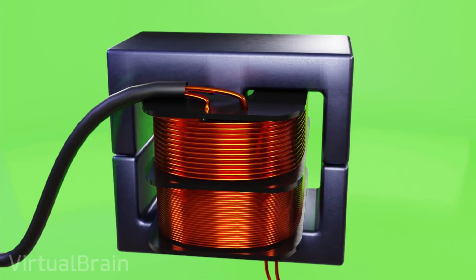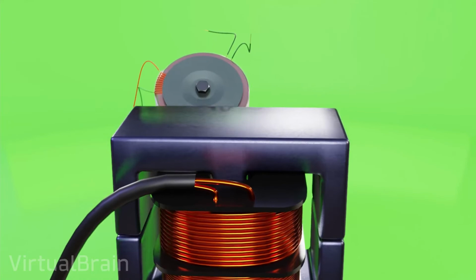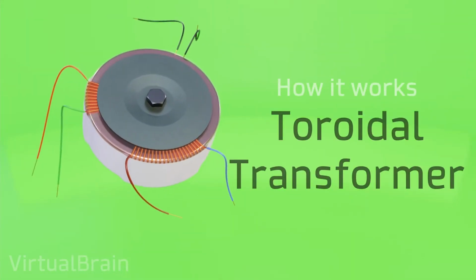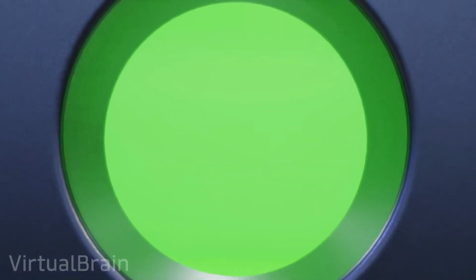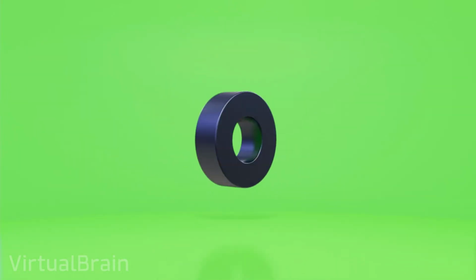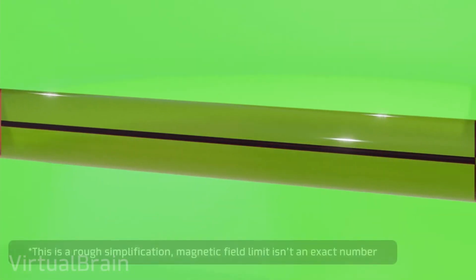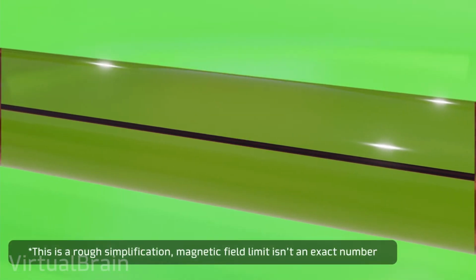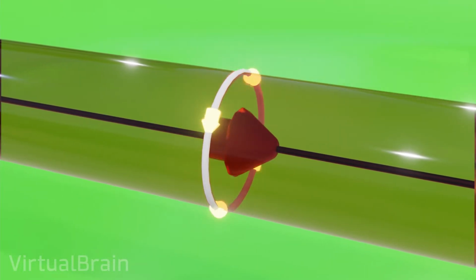But transformers like the ones I showed you in the previous chapter still have certain limitations. And that is why in this chapter we will see how a toroidal transformer works. We will start by analyzing the obvious: why use a toroidal shape? This has to do with the shape of the magnetic field and flux generated by the primary coil. If we have a straight wire, the magnetic field will take the shape of a cylinder, and the magnetic flux will be perpendicular to the direction of the wire, basically forming a circle.